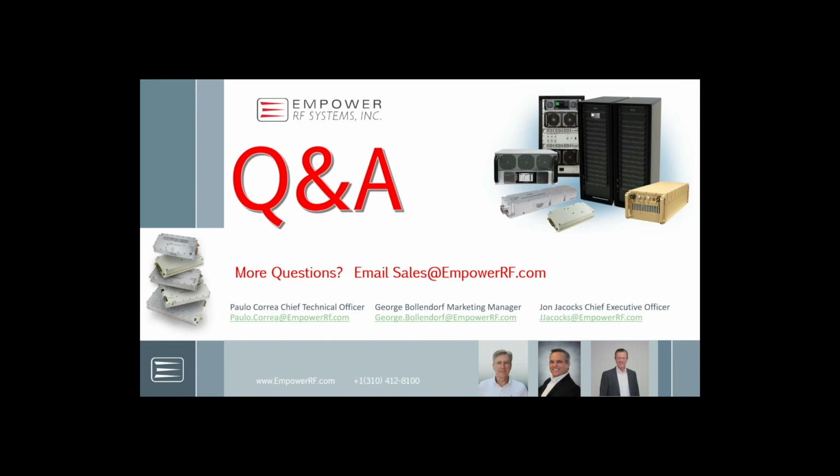So it's not very easy to know that. Usually what we do is that we don't allow the base plate to be higher than 85 degrees C. We protect it at 85 degrees C at the point where we can measure the temperature. Our thermal sensor is very close to the case of the device, and we can measure with very good accuracy the temperature of the flange.